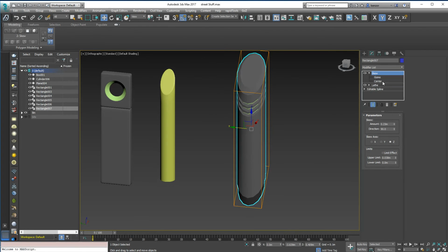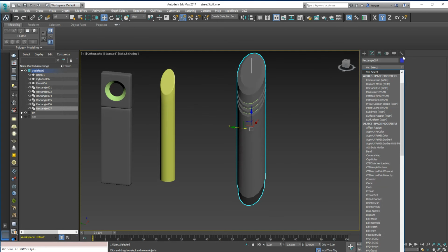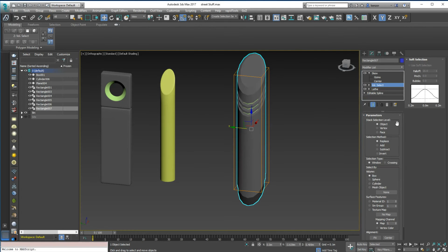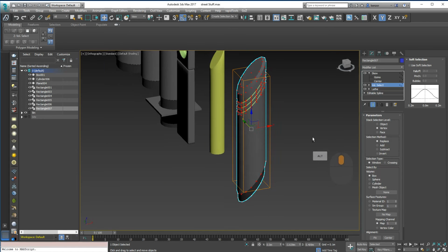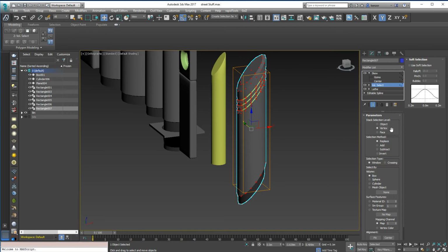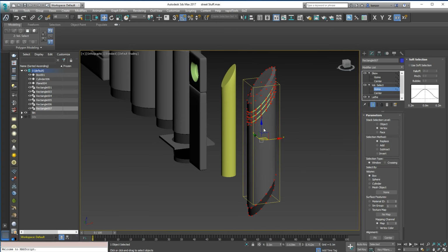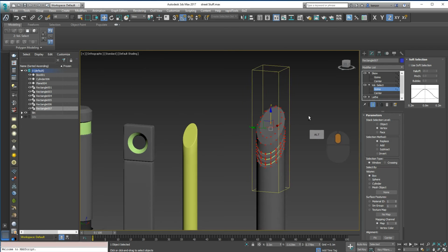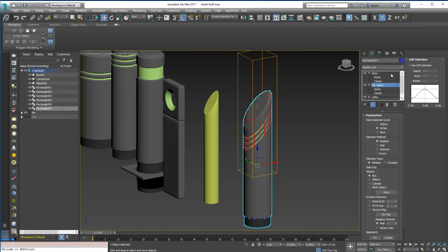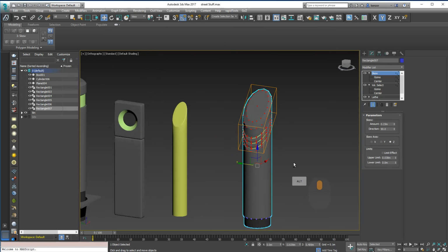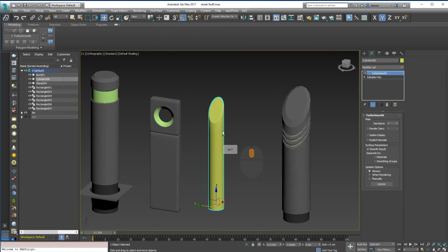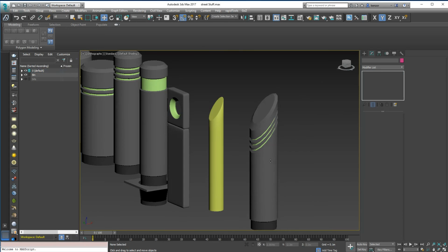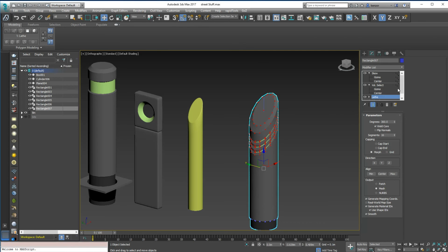And what I'm going to do is use a volume select tool, select vertices, and I'm going to replace them, and now I can drag that gizmo up and down, and that will define the selection area for my skew, like that simply. So this is like a destructive method. The effect is baked in, and this is a non-destructive method. So I can now go back and say change the number of lathe segments, and the skew effect remains.